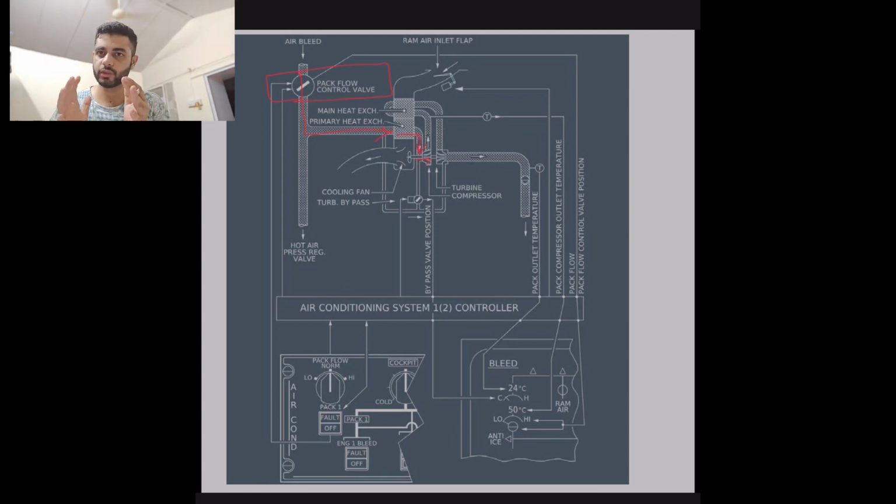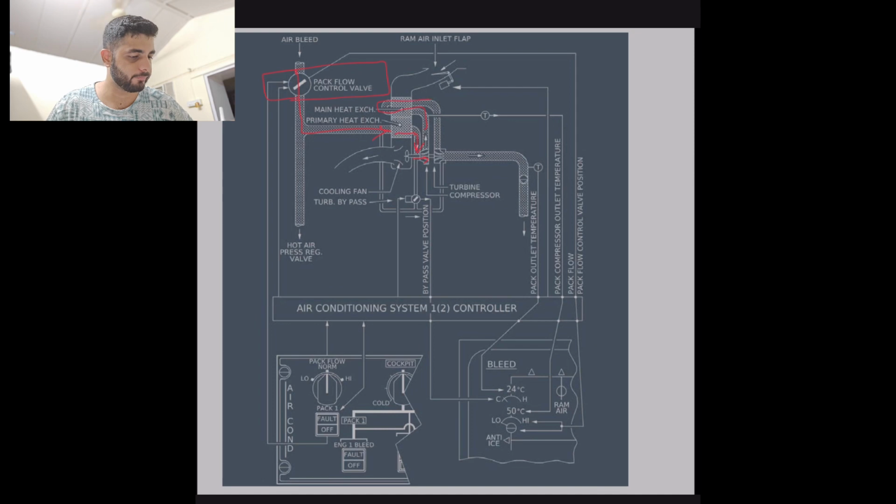When the air gets squeezed, the air heats up. Now because the air heats up so much, it must go through the heat exchanger again, twice, because the air is very hot. So it goes through the heat exchanger twice. And then it comes to a turbine because something has to run this compressor. So this turbine that is there, it runs the compressor. Now because you're running a turbine, further cooling of the air happens.